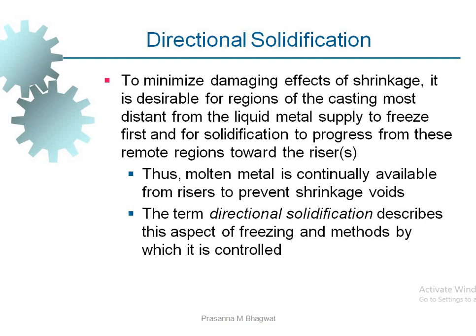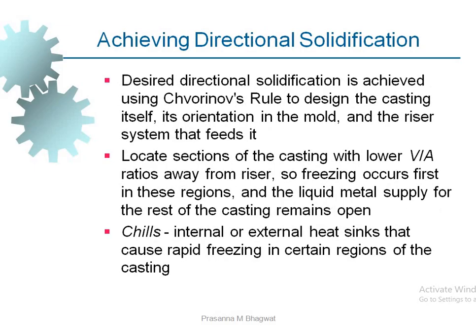So, the part of the casting which is away from the riser should solidify first, and from that particular point it will end in the riser, so that it will provide a proper solidification process and will not create any shrinkage defects. The term directional solidification describes this aspect of freezing, and the methods by which it is controlled.